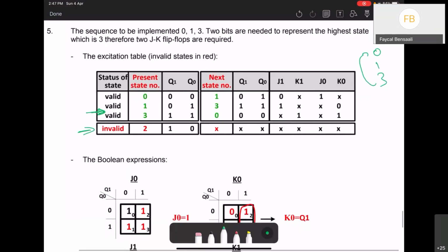Right. Here, to do the solution, I put X. And as you know, I'm going to use JK flip-flops. For each one, I will have J0, K0, and then J1, K1. So I will have 4 outputs now. It's not just 2 like D0 and D1. Inputs, which are J0 and K0, and then J1 and K1. And then, of course, for the rest I will guess the zeros and ones. I will just follow the excitation table for the JK flip-flop, going one by one.